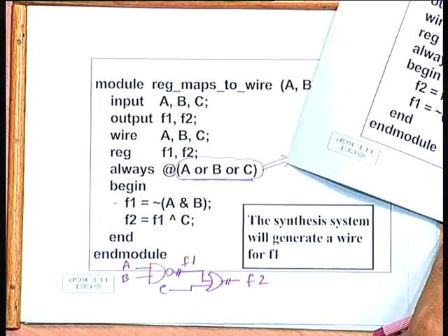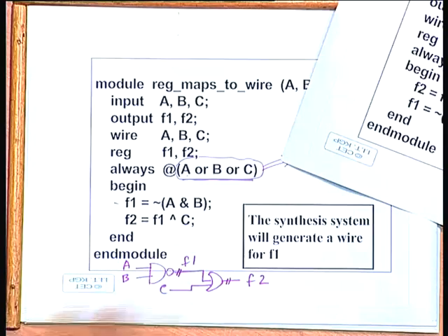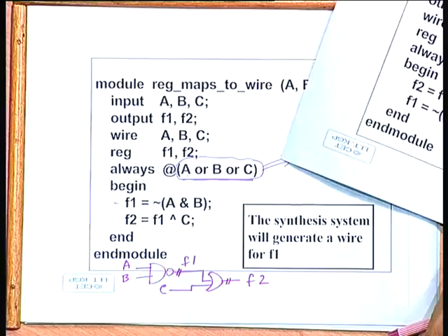So if you wanted the old value, you would explicitly have to mention a latch or something. If you required the old value, you would have to specify it in a different way. That we will see, how we will specify that. The chain of values of F2 will depend on the delays of the gates as it goes on. So when you simulate this, you will see in the timing diagram that after some delay the values are getting changed or computed. Yes.